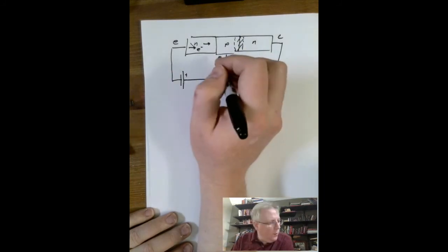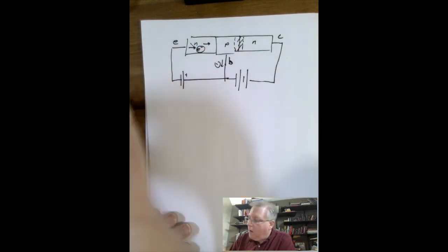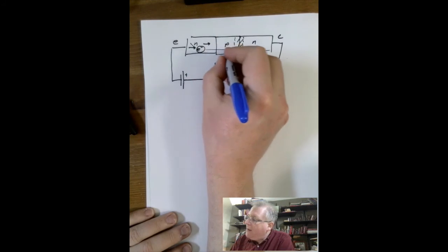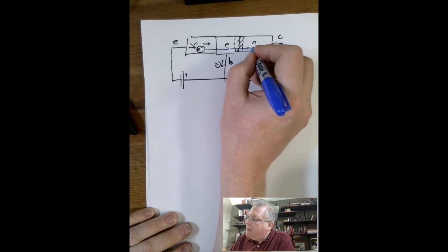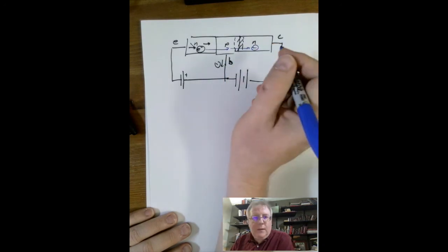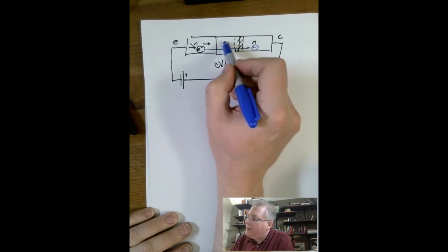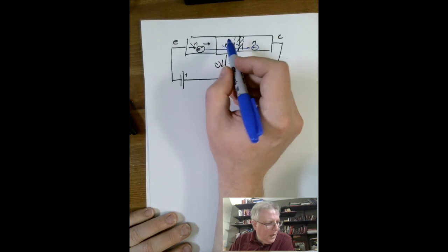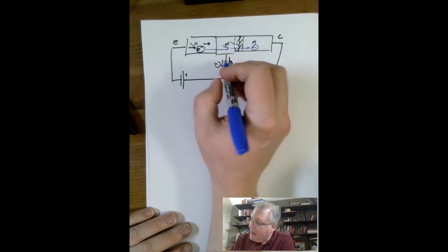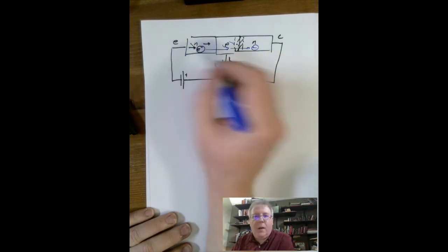But here's how this works essentially: these electrons that I've injected in here can keep going right through the P-type silicon and make their way over into the N-type silicon. So I now have charge carriers that can do this, and they can only get through if I've got a voltage here to create more charge carriers in this region. Basically, by creating a small voltage between here and here, we can create a big current between here and here.